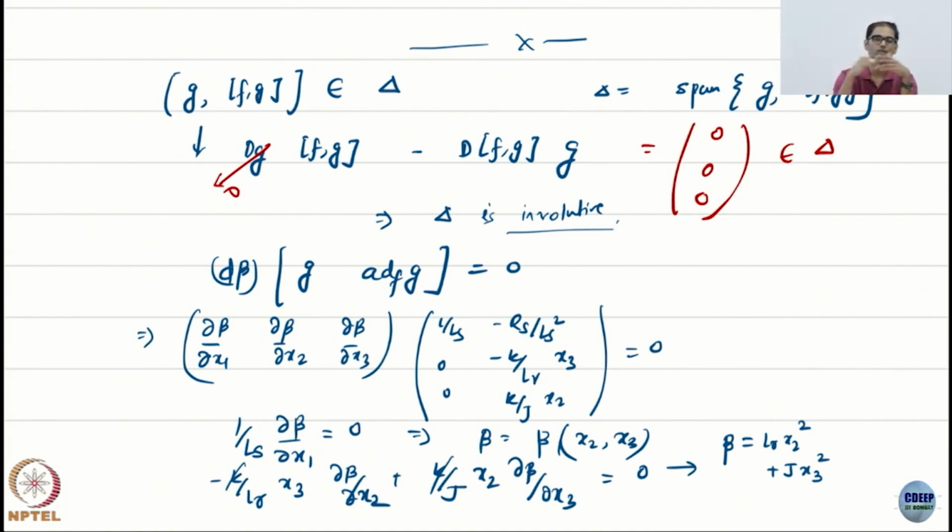If you have some robot dynamics, like a mobile robot dynamics, which you can feedback linearize, then you can say a lot of things. Even if you have 1,000 such mobile robots, you can still control them with seemingly easier control laws. Of course, this nonlinear transformation will play a big role, but the good thing is it's just a transformation now. It's just going from one function forward and one function backward. Everything can be transformed like that.